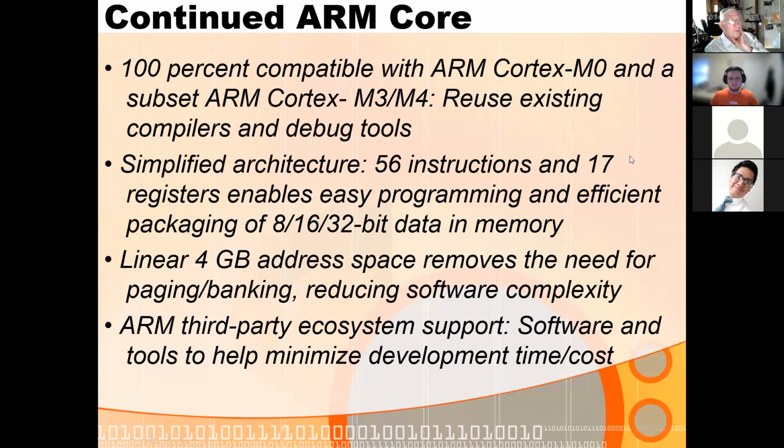So there are specific assembly language instructions that will sign extend if it's a 2's complement value, or zero extend if it's an integer value. So there are some considerations, because you're using 32-bit registers when you're dealing in bytes and half words, about what to do with the remaining bytes in the 32-bit register.